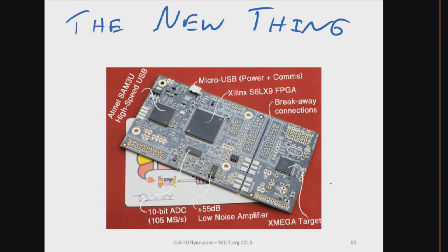So this is the board, and basically half of the board is programmed with an algorithm of interest. In this case, I'm just doing research type work I'm showing you. I'm not attacking a commercially available device. I've taken this device and programmed it with an open source AES implementation. This one is AVR CryptoLib, but there's a few other implementations you can test.